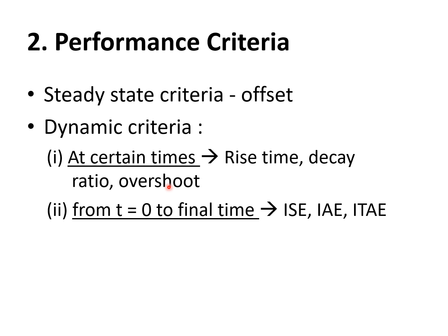But if you want a dynamic criteria that covers from the beginning until the end, then we have to use the more rigorous methods: the ISE integral square error method, the IAE integral absolute error method, the ITAE integral time absolute error method. These are more detailed and more comprehensive, covering from the beginning until the end. But again, as I said before, in the real world we may have to use all these criteria together.